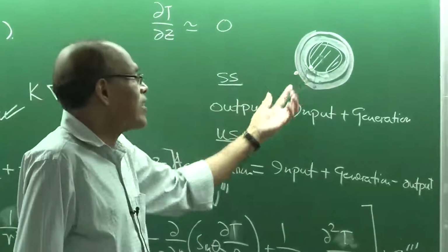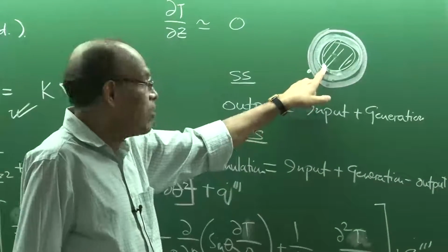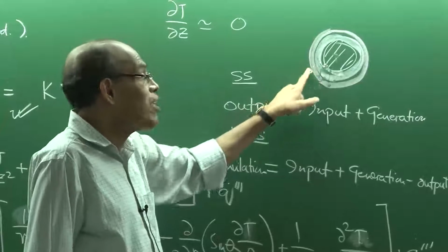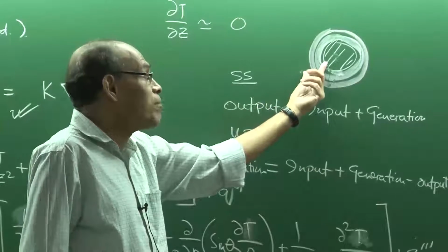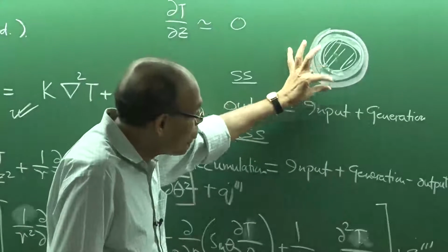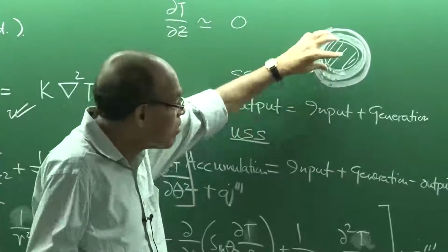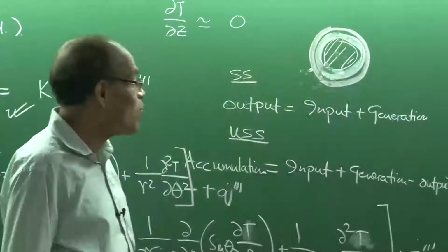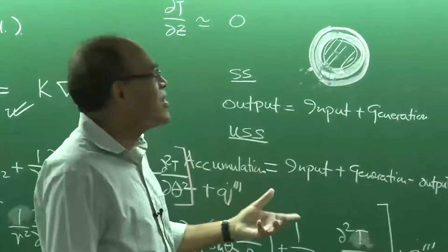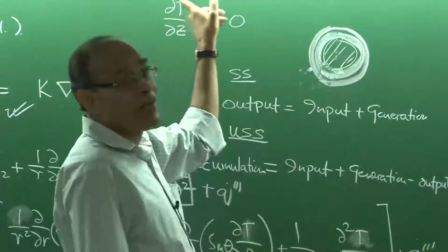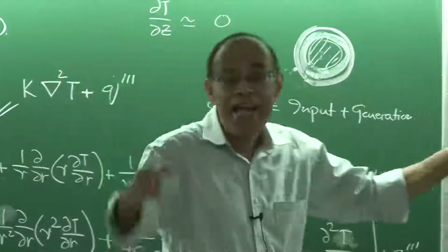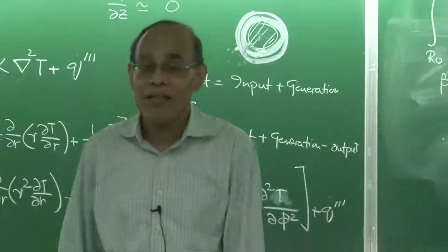So, in this particular case, if you know these temperatures, these are boundary temperatures, and the thickness of the coatings on this circular tube is also given to us, then we should very easily find out the net rate of heat flow by simply adding up the individual thermal resistances.